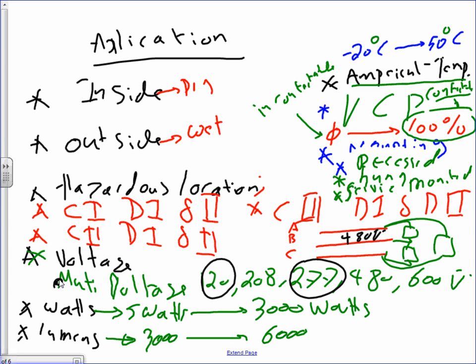Then the last thing, I don't know if you guys can read my handwriting, but believe it or not, this word is mounting. When you have a fixture, you need to mount the fixture, right? How do we mount the fixture? Kerry, my friend, you were throwing all your fixtures in our project, and you were asking me, Chad, is it recessed? Recessed like these, right? Is it suspended? First, recessed, suspended, surface mounted, wall mounted, right? Either you surface mount it, or recess it in the ceiling, or suspend it from the ceiling. So these are your options. You have recessed, surface mounted, or suspended or hung. You hang it. Any question, guys, about these methods for the most part?